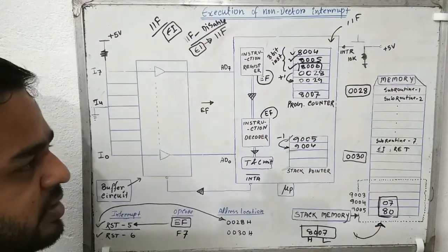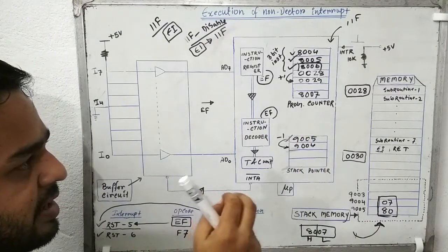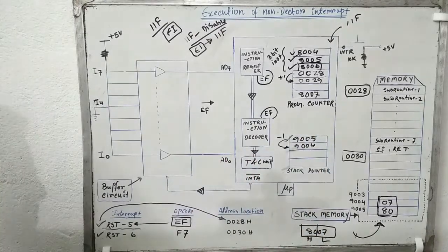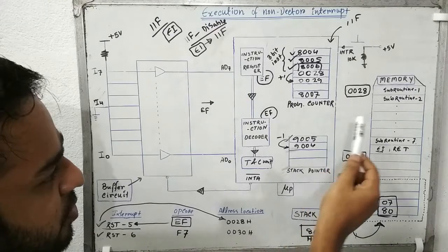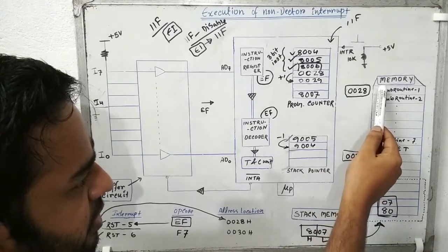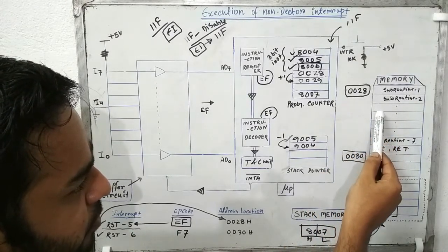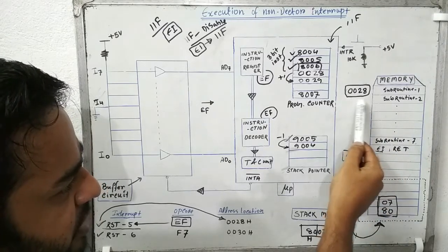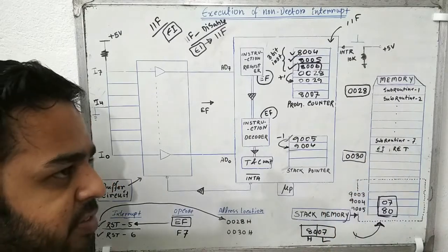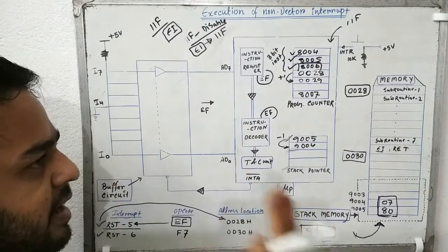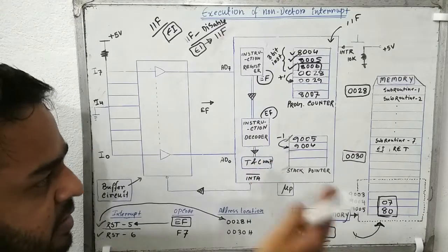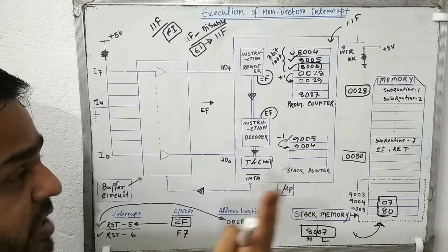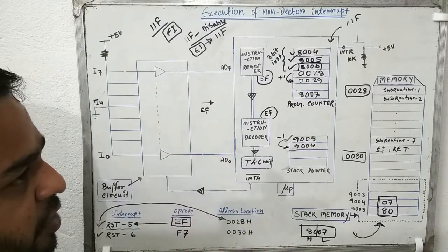Then the microprocessor will immediately start to process the interrupt request. How does it process those interrupt requests? It processes them by executing all those subroutines which have already been written into a specific address location. When all the subroutines have been executed, the microprocessor completes the execution of the interrupt request. Then it comes back to the main program which it had been performing for a long time.